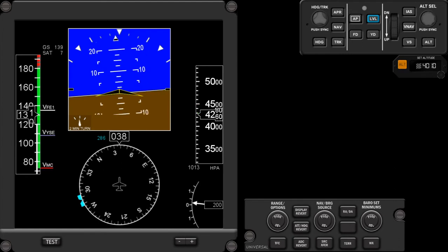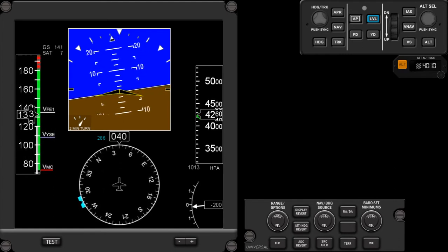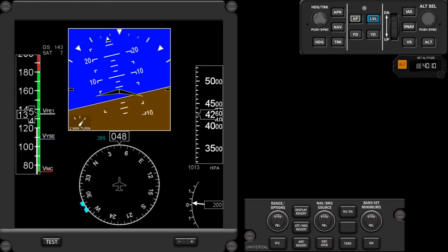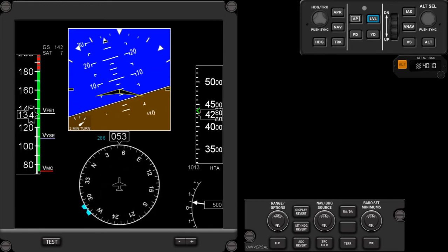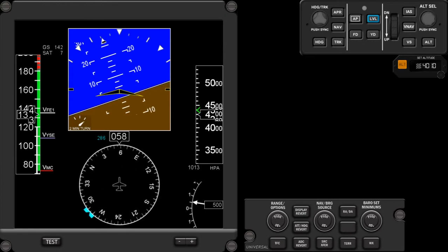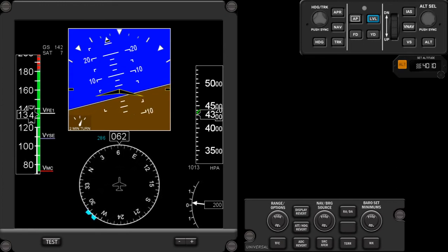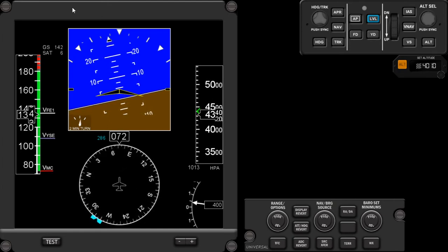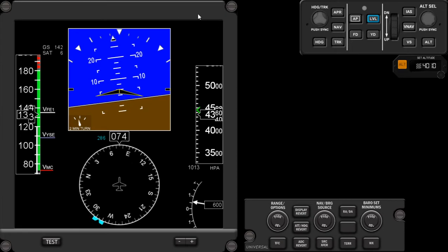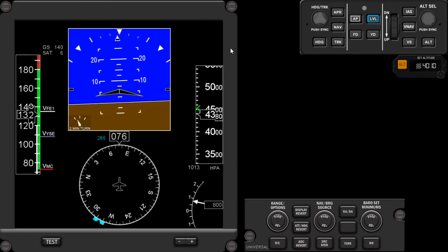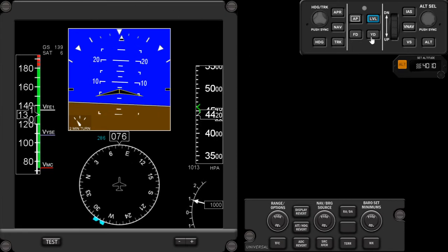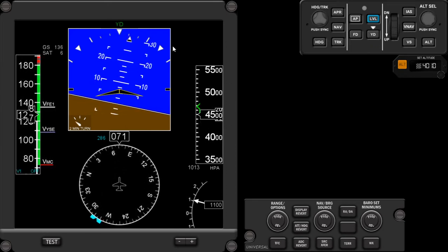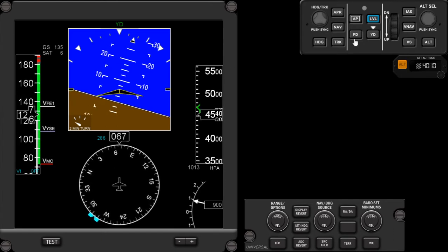So now to some other features of this avionics unit. First of all, we will see the autopilot annunciator, the flight mode annunciator, yaw damper, flight director, and so on. So now I'm hand flying with everything switched off. So in this upper part of the instrument there are no indications. Now I will turn on the yaw damper, and I can see the yaw damper is running and I'm still flying manually. Now let's turn on the flight director.